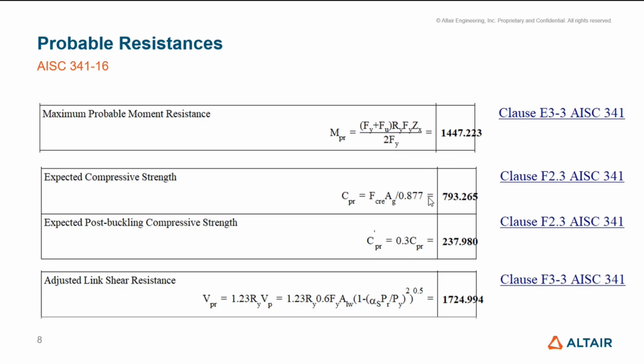So this ratio ranges between 1.1 to 1.6 depending on the steel grade. So essentially the code wants to make sure that the expected resistance of yielding members is calculated as realistically as possible, considering actual, not specified, yield stress.